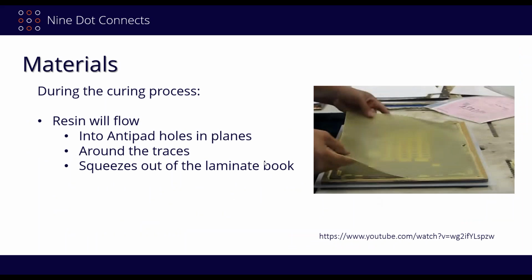Anyways, for material, this is one I wanted to show you over here. So here's a great example of prepreg, and you see that it's kind of mushy. You can wave it around. It's not rigid or stiff. And then what you see happening over here is they're actually doing the layer stack up. If you look just below that, you see that there's the copper that's already been etched out on this prior layer. That's probably a core material that's being placed there, and now they're placing the prepreg on top of this, and then they'll probably put another core material, or if this is the top of it, they'll put the copper foil on that next.